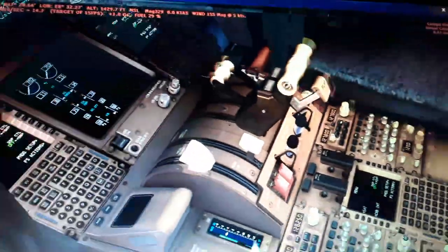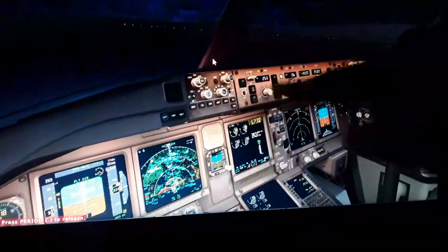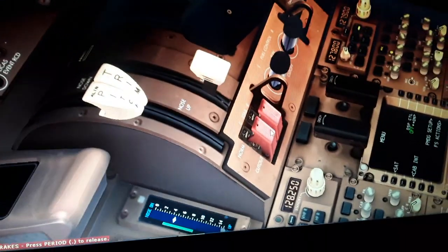So the horizontal trim stabilizer, very important. If you have a failure of the hydraulic system, the left or the right, C or R, the auto trim I told you about, the autopilot and the auto throttle will have a malfunction, so you'll have to disconnect. Open this guarded switch here, disconnect the stabilizer from the normal, to cut out.